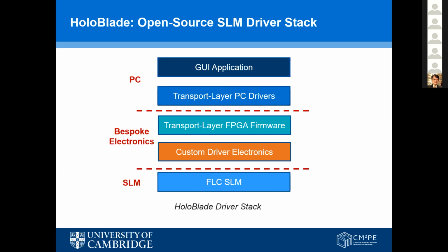On that board we have our own FPGA, where we've implemented all of our own higher level logic to marshal the data as it comes from the PC. Those comms use USB 3, which then talks to the PC, where we've put together a bunch of PC drivers, which talk to a GUI application that we've put together to demonstrate the application.